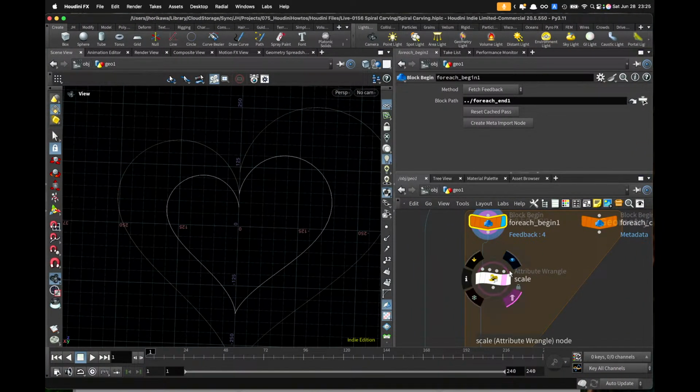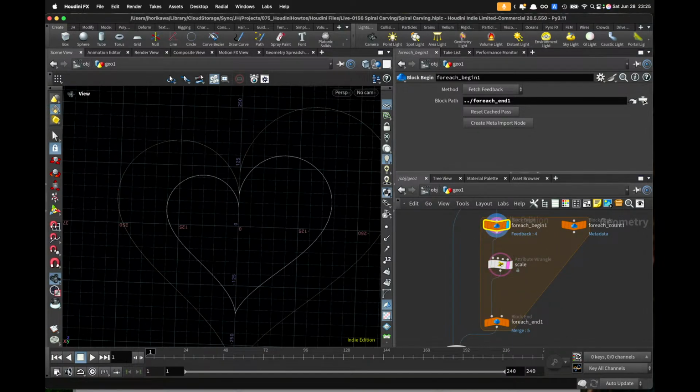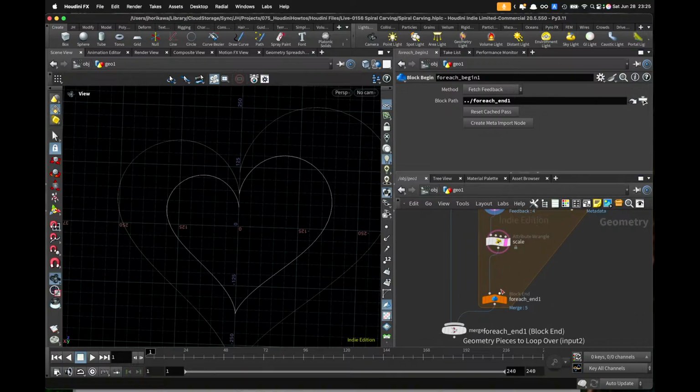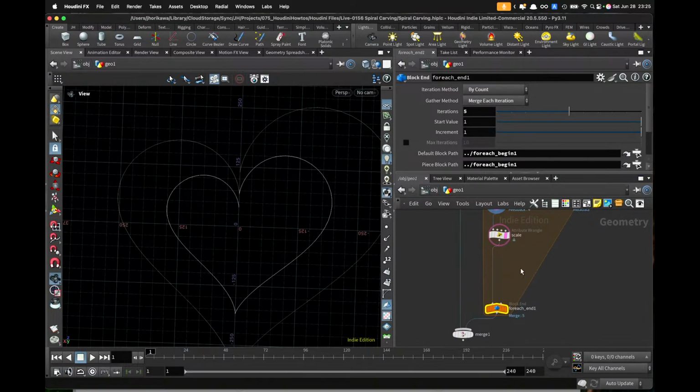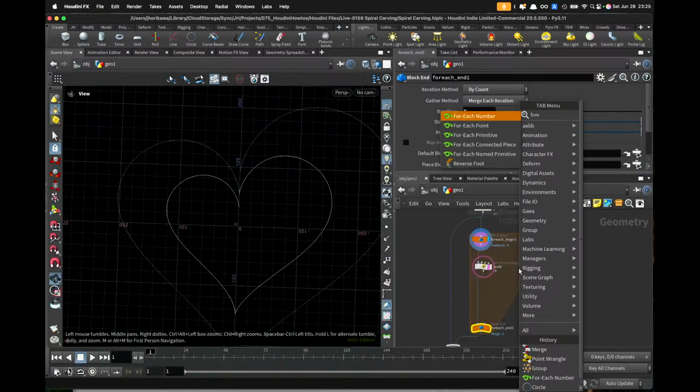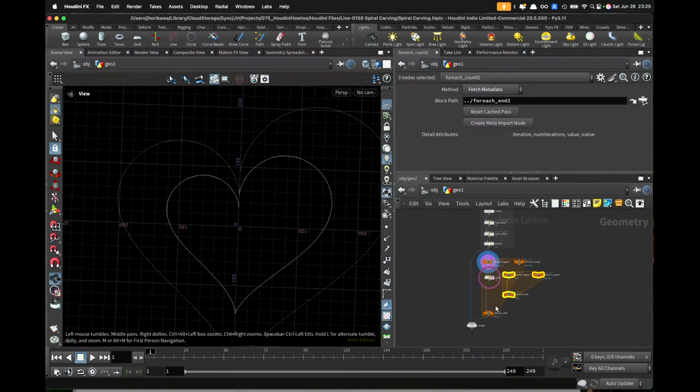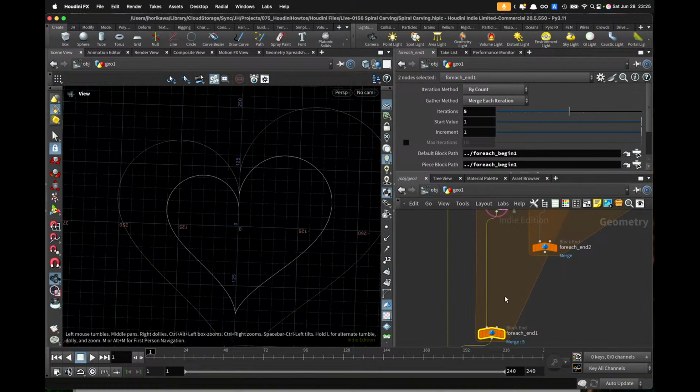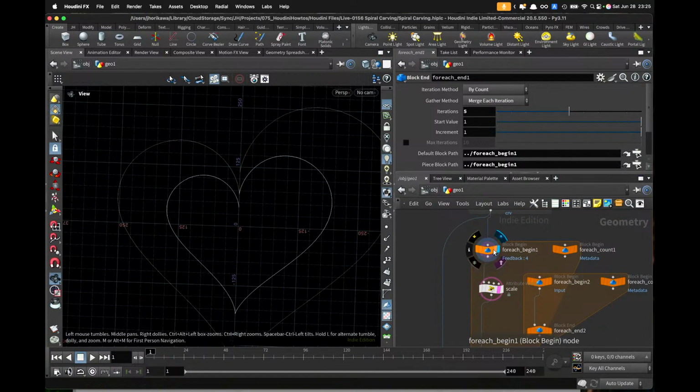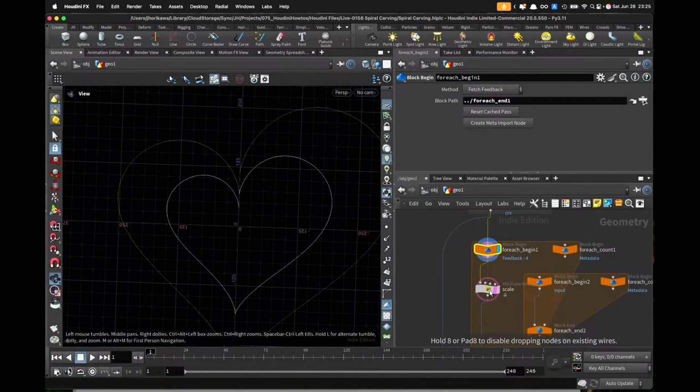Okay, so in order to do that, what I would need to do is to first of all specify how many divisions you want for each surface in between the curve and the next curve, the scaled curve. So I'm going to have another for loop inside this loop to decide how many layers, how many divisions you want for a surface in between the original curve and the scaled curve.